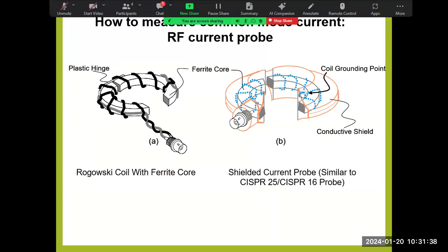One of the tools we use, since we talked about differential mode and common mode current: for EMC, often for emissions and for picking up noise that's radiated, common mode current is the most important aspect of the way things are working. So it's good to be able to measure the current somehow. It's a high frequency AC current. So there's a technology for current probes.